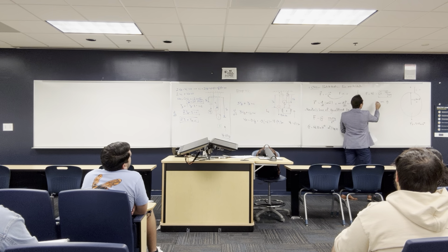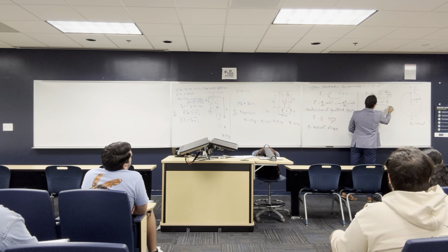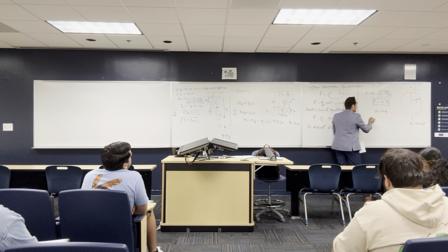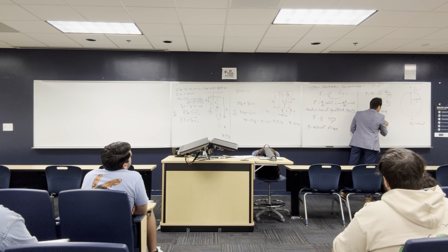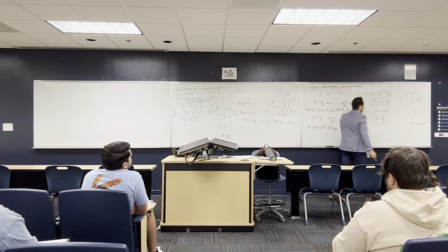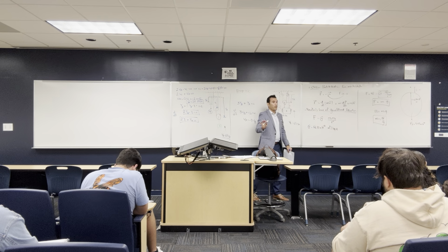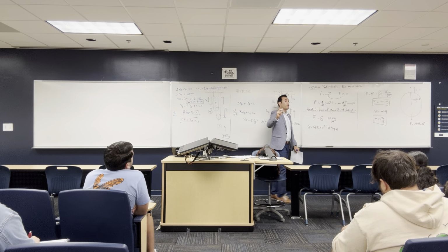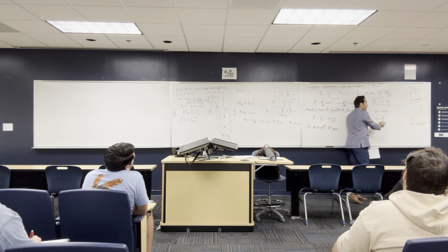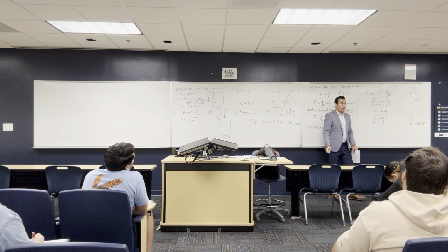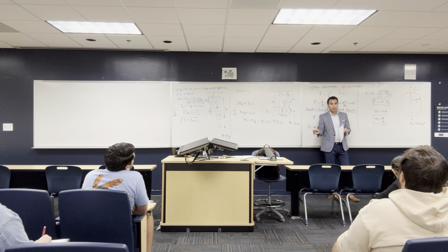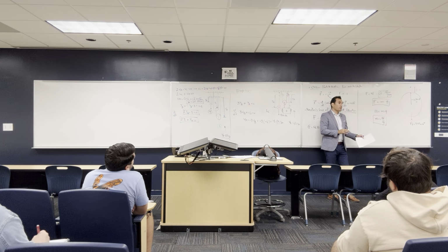Anyway, so we have F equal to mg, and that's what we call the weight of the body, equal to m multiplied by g, and then you can get the mass by dividing W over g. So be careful in problems. If I give you a problem saying that a body has a weight of 10 Newton, that's W. And if you want to find the mass, you need to divide by g. And anything that is in kilograms means it's a mass. And anything that is in Newton means it's W.